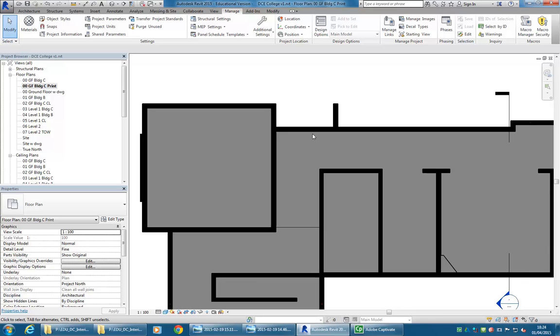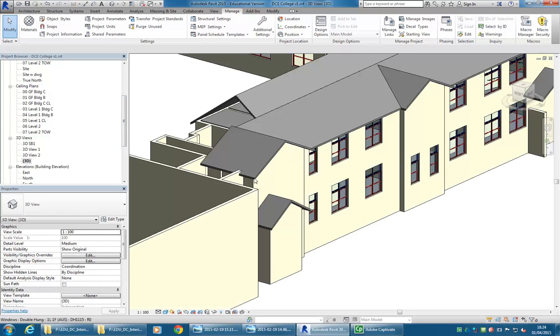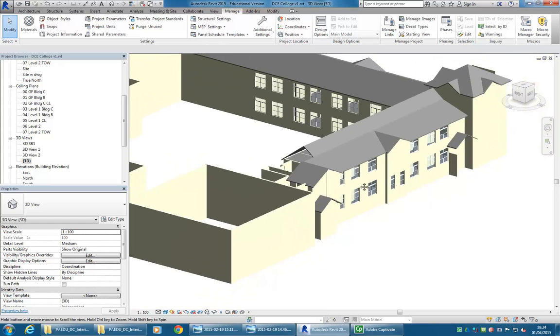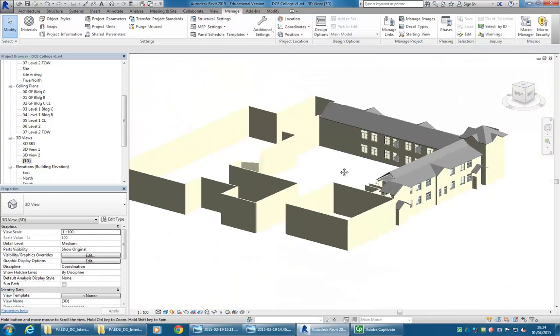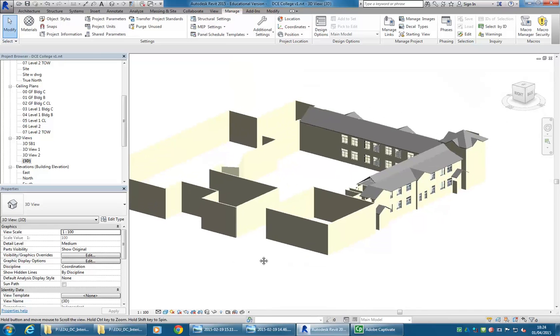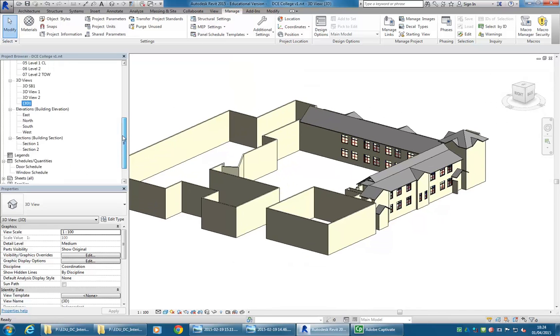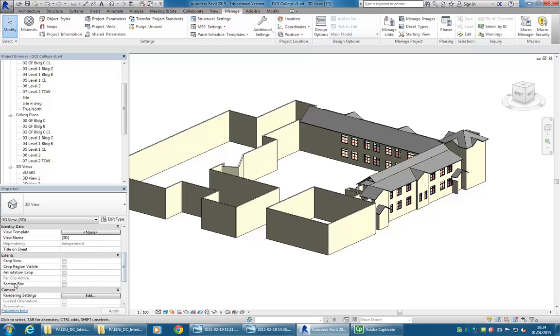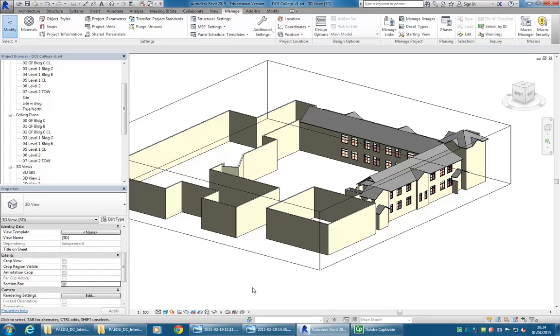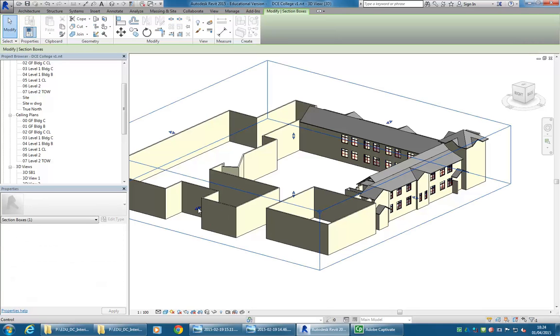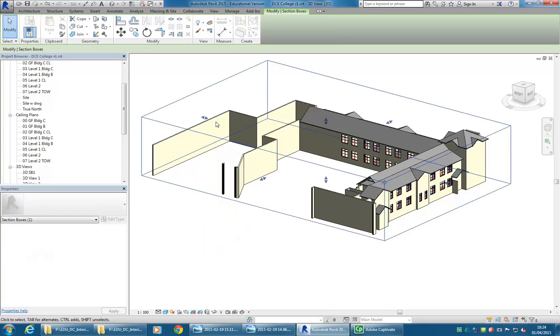And it's one of those things, again, that's not all that obvious at first in Revit, that you have that choice. And so now, back in my 3D view, you can see it's still using the shading colour for the outside. But an interesting thing there, if I cut this, so I'm going to maybe remind you, if you haven't done this for a while, to cut in 3D, you can use the section box. So turn that on, and I'll cut through part of this building.